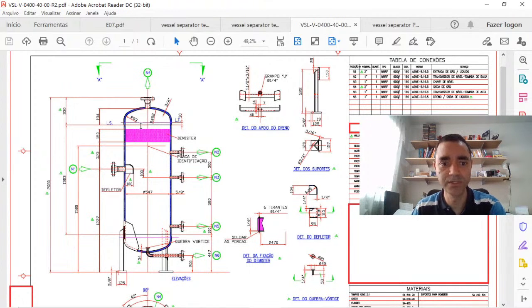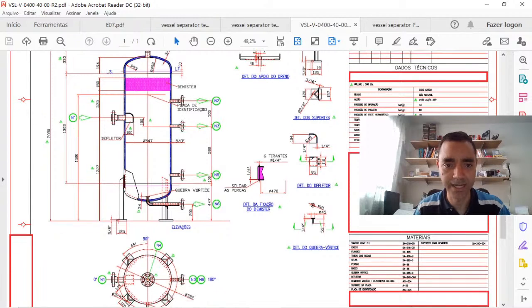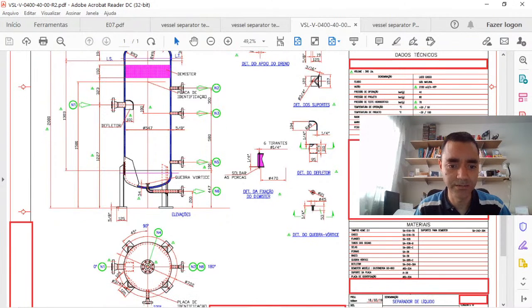But before building the equipment, in some projects I worked on, we have, for instance, 10 days to comment on the manufacturer drawings to confirm that the nozzle is in the correct size, and if the direction of the nozzles is correct.